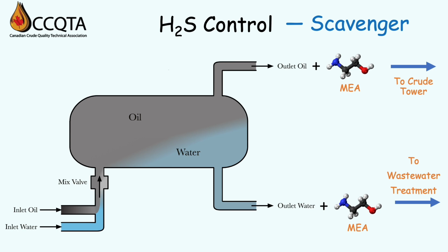In the wash water, ethanolamines are toxic to aquatic life and kill the good bacteria used in the wastewater treatment process, causing upsets and the potential for water quality issues, hence additional treatment is required. Triazine and dithiazine are both biodegradable, so they have limited impact. However, just like we talked about, the MEA triazine reaction produces MEA, so the toxicity is similar.